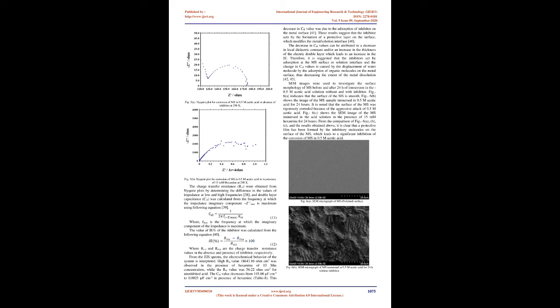The behavior can be interpreted on the basis that increasing temperature leads to an increase in the desorption of the adsorbed inhibitor molecules from the MS surface. The values of ΔS°ads were large and negative, which is accompanied by an exothermic adsorption process. From Table 6, the negative values of ΔS°ads describe an ordered phenomenon. This order may probably be explained by the possible formation of a metal complex on the MS surface 35.